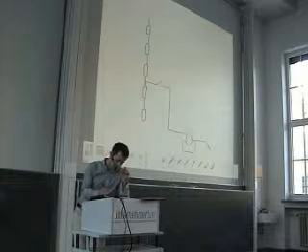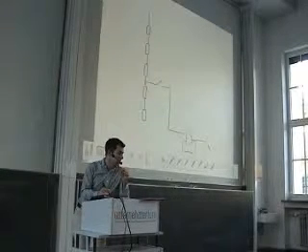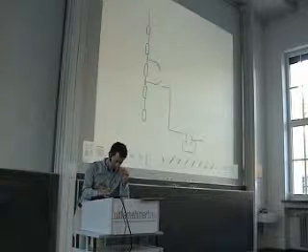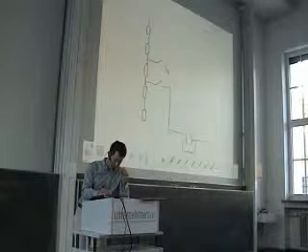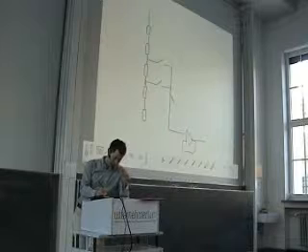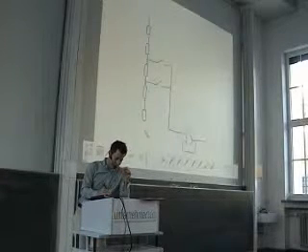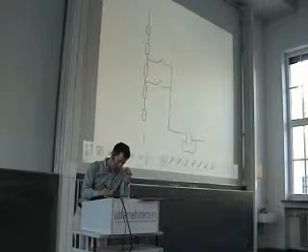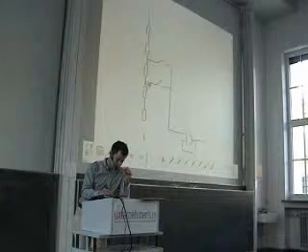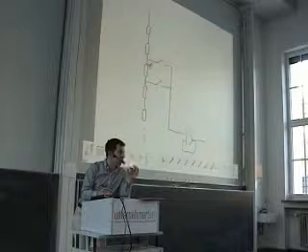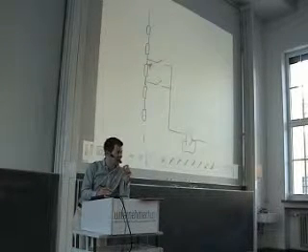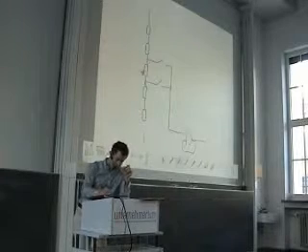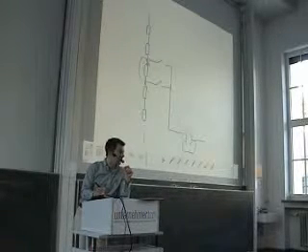Well, then if I increase the input by 1 LSB, I go from this switch to this switch. So you can see that the output voltage always increases when I come from this node to this one. The worst thing that can happen is that this resistor becomes 0 because it is shorted or whatever.